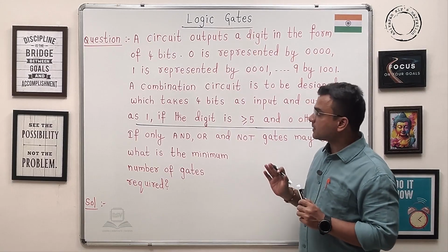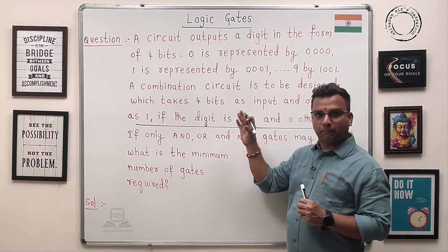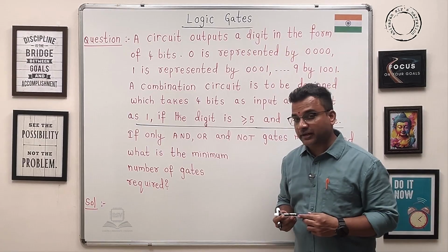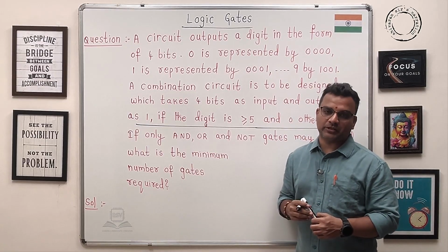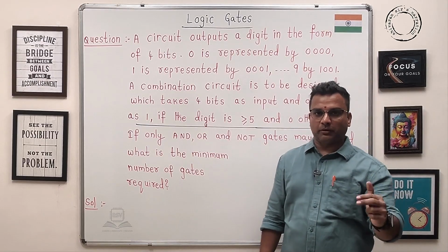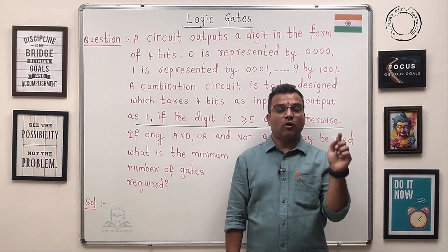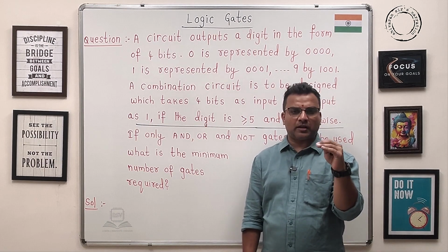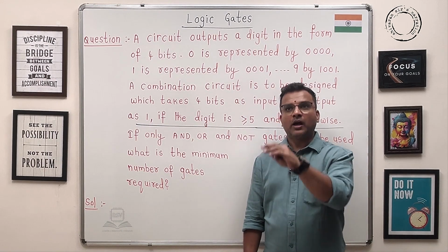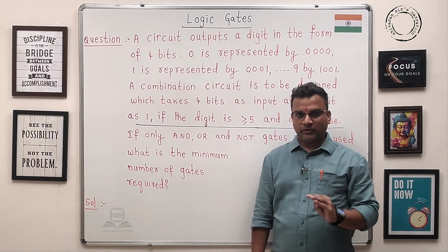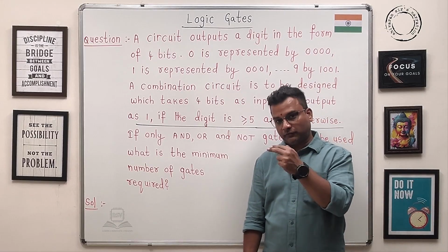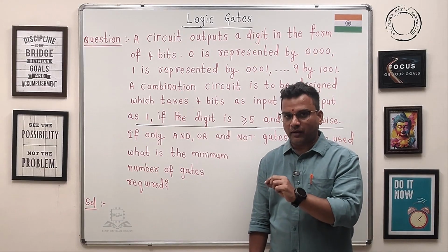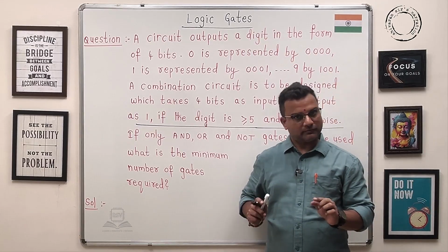Now here guys, as 4 bits are present, how many combinations do we get? 16 combinations. If you write the truth table from 0000 to 1111, inputs up to 0100 give outputs of zero only. From 0101 onwards till 1111, the output becomes 1, right?